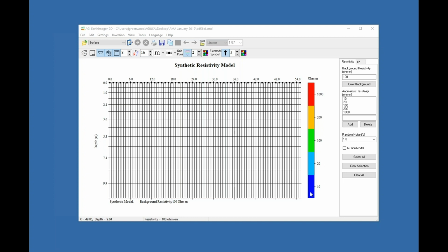So that leads into another question. If you're designing your exploration depth, which is a function of the length of the line, you should have your target in the upper half of the model section, because down here you see how coarse the mesh is, and that's a function with any surface geophysical method where your sensor's at the surface. You always lose resolution with depth. So this is not where you want your target.